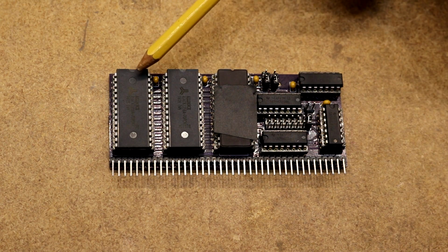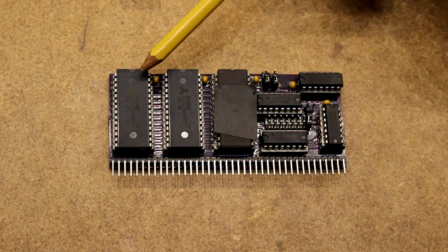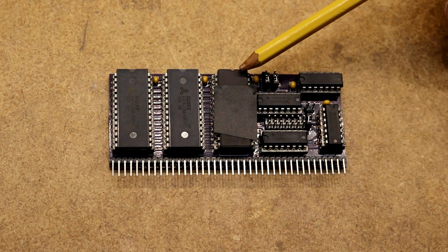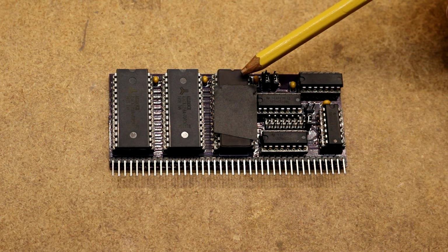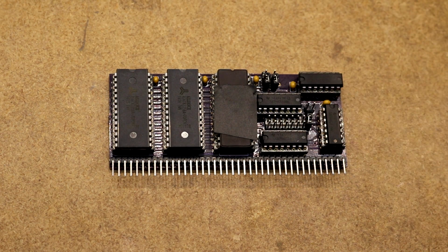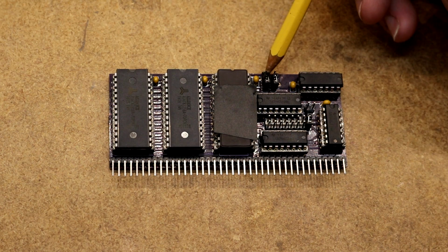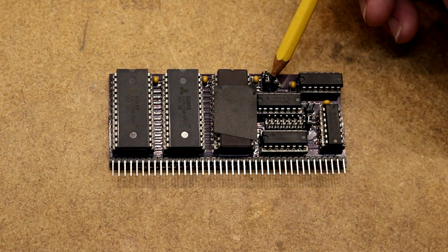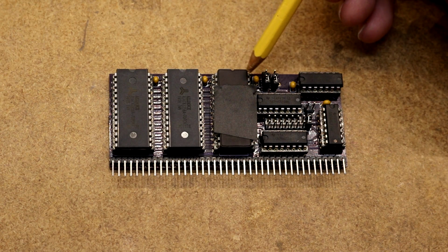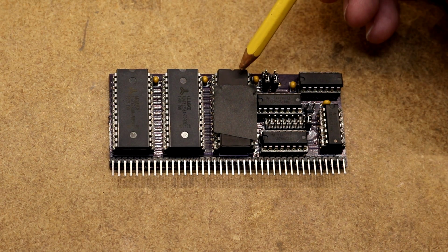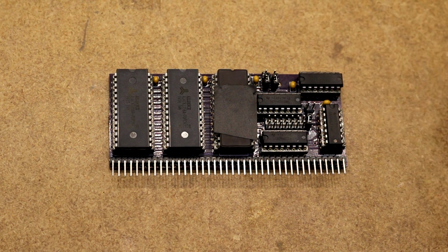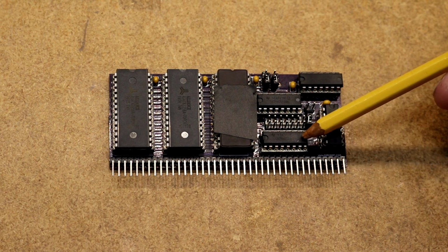So we have two RAM chips. They're the 62256, 32K each. That's this chip and this chip. We have the 27C512 EEPROM. I put a piece of black tape over the window so it doesn't get inadvertently erased. These two jumpers allow you to select which 16K window of the EEPROM you want to use, so we can load up to 4 different bootloaders in the EEPROM and select between them with jumpers. Over here we have our 3 to 8 decoder.